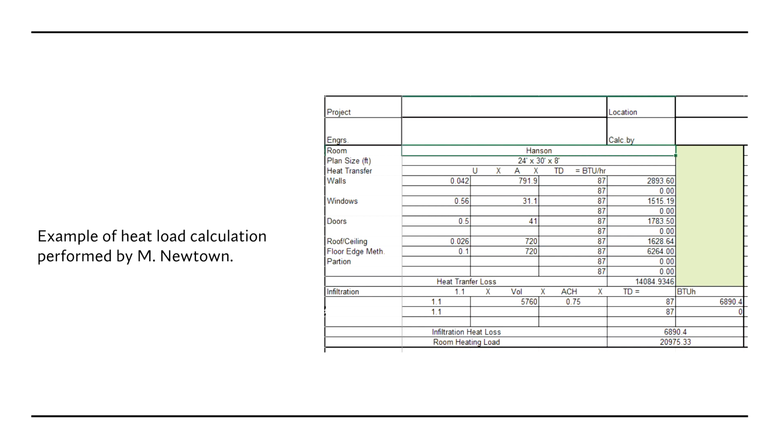Generally we're looking at this. We need to know the volume of the building. We need to know the area of the floor, the ceiling, the area of the walls, and then we're going to measure the areas of the windows and the doors and anything else that's going to allow energy to transfer from indoors to outdoors or outdoors to indoors. And it depends on the season. So the easiest way to qualify that is we do one for cooling and we do one for heating.